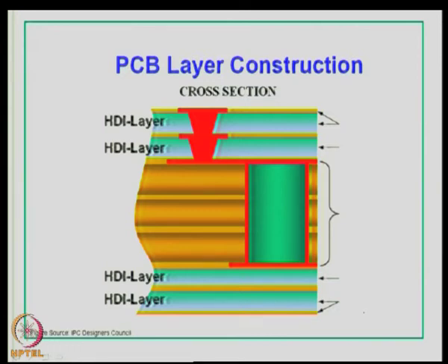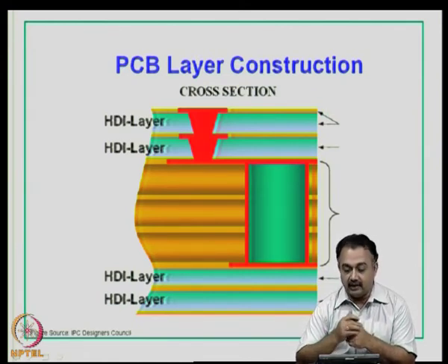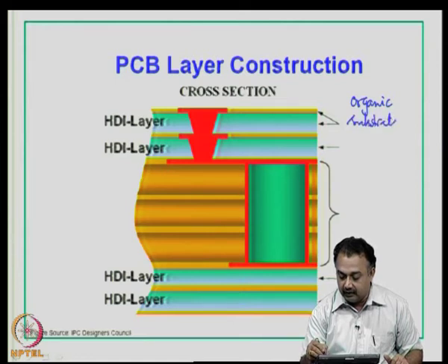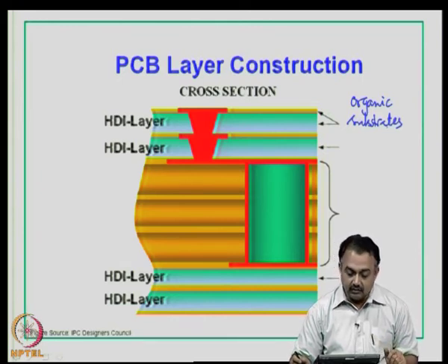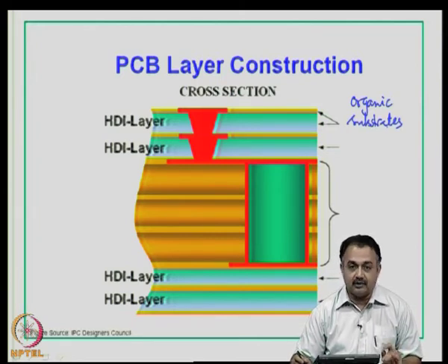Now, we have been talking about printed circuit board or organic substrate which resembles a printed circuit board in these packages, in a BGA package or a CSP, for example. And you must know that these organic substrates that are being used which support the die have very high density interconnect structures. So, I want to pull out some of the slides which normally we discuss in the technology to give you some idea about what a cross section of an organic substrate will look like.